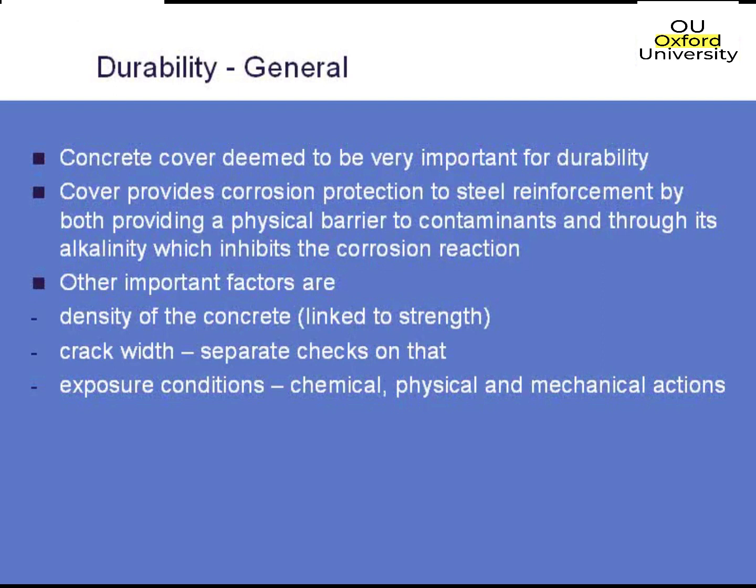Crack width does have some effect. You can't have really big crack widths occurring. If you've got a 3 centimeter crack width, for instance, it is going to let contaminants in, and that's why you've got the 0.3 millimeter crack width limitation. And then the exposure conditions will also affect your durability. Obviously, if you're in a harsh environment, it's going to start breaking down the concrete, while a piece of concrete that's sitting inside won't be affected nearly as much. So that has to be taken into account as well.